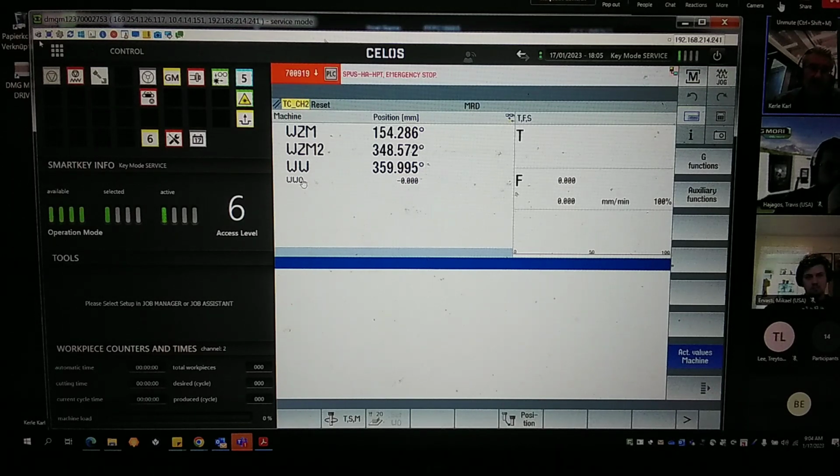That means in this configuration, the processor responsible for positioning and the axis control mechanism needs double the time to evaluate the position signal of the encoder and of the direct measuring system, okay? So we need a bigger range of cycle time, and this limits the maximum number of axes in channel 1, okay?